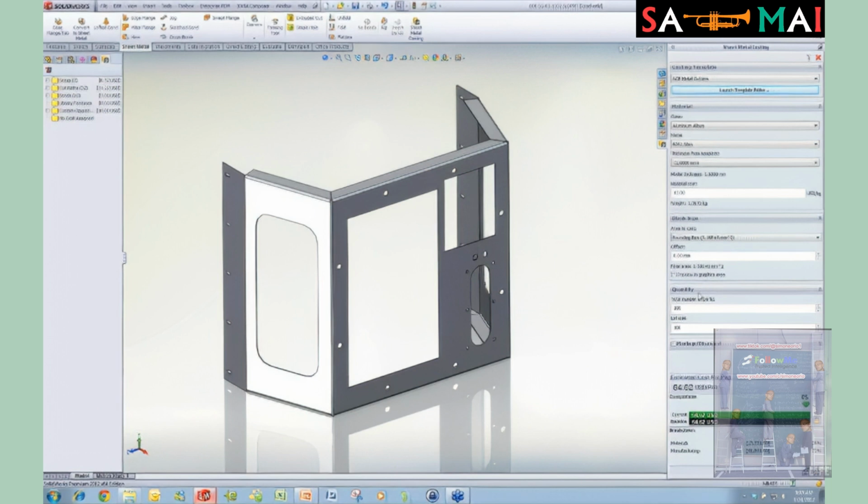Moving down here for the quantity. So right now everything's based on a quantity of 100. So we've got 100 parts and the lot size is 100. So we're going to run all 100 parts at one time to get that done. I'll show you in a minute when we change that how it's going to affect the cost and maybe why. So the markup and discount, one more under here, is we can, say for our markup, increase it by 10% of the total cost, maybe for a shop rate or something, or increase the material cost alone. We can fudge the numbers a little bit there if you wanted to.